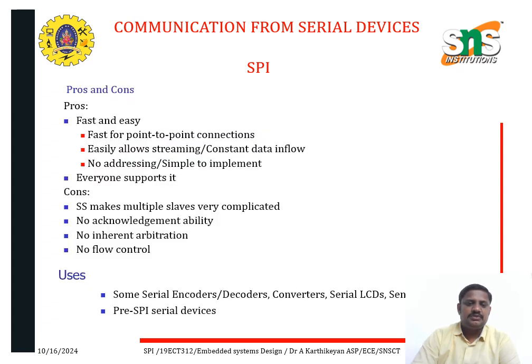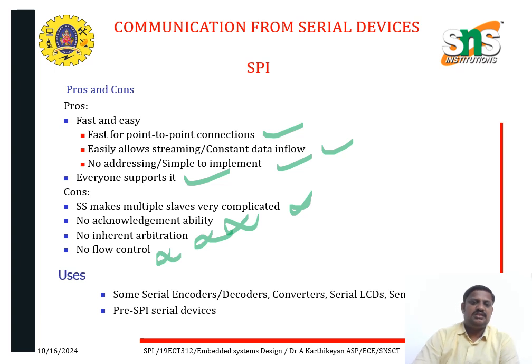Now the SPI pros and cons. The pros: it is a fast and easy transfer, with point-to-point connections, easy streaming of constant data, no addressing, and everyone supports it. The cons: multiple slaves are very complicated, there is no acknowledgement, no error checking, and no flow control. These are the main cons of SPI.